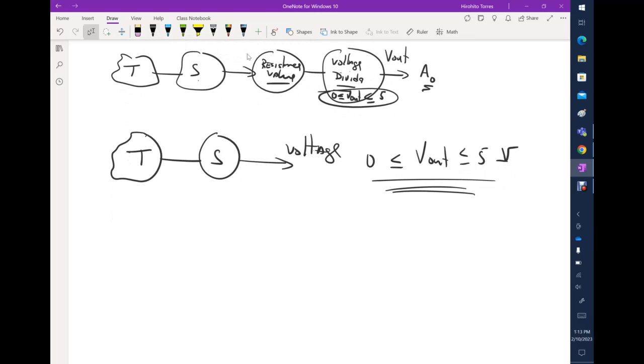So I just want to be sure that you understand this type of sensor, that there are basically two kinds. One, where the change in the physical property you are trying to measure is a resistance value. Those need a voltage divider to be able to accommodate them into the Arduino. On the other hand, if the sensor already produces voltage, this is perfect, you are done.